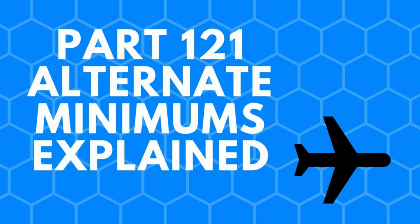Domestic Part 121 operators must also file for alternate airports when the weather at their destination airport, from 1 hour before to 1 hour after their ETA, is forecast to be below a 2,000-foot ceiling and/or less than 3 miles visibility. For alternate airports with at least one operational navigational facility that provides a straight-in non-precision approach, a straight-in precision approach, or a circling maneuver from an instrument approach procedure, determine the ceiling and visibility by: